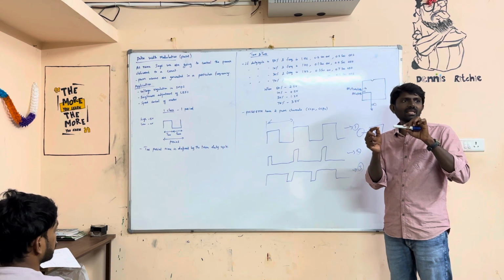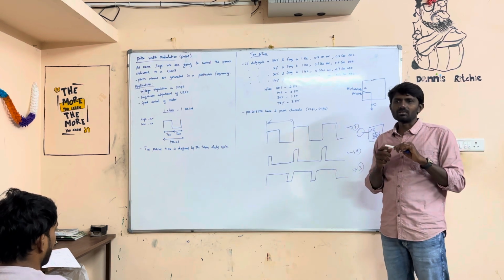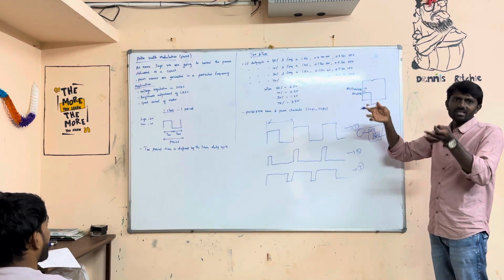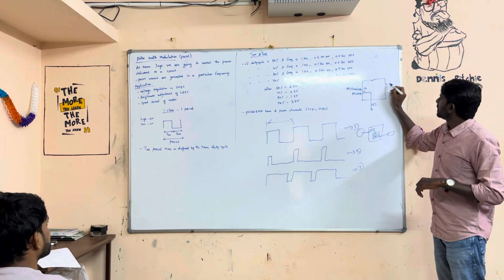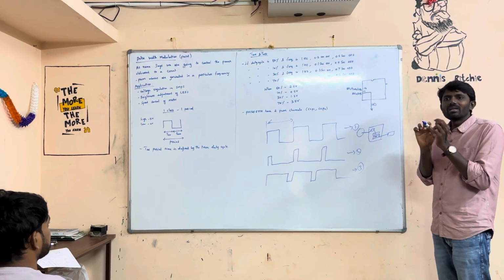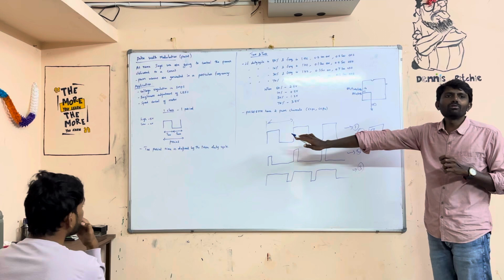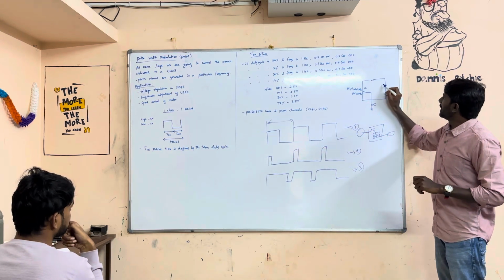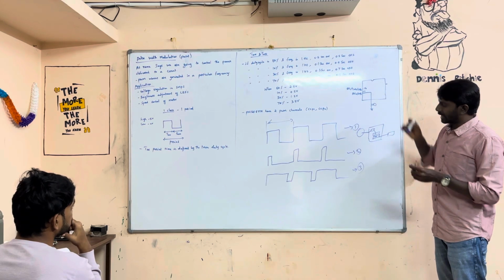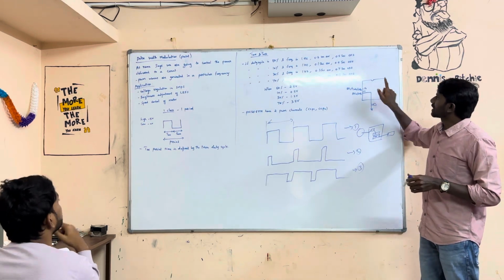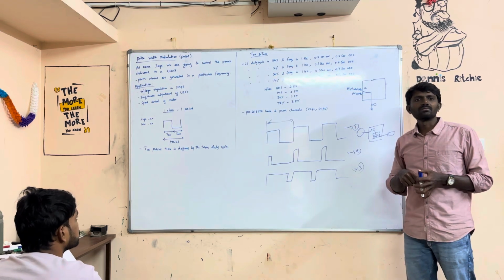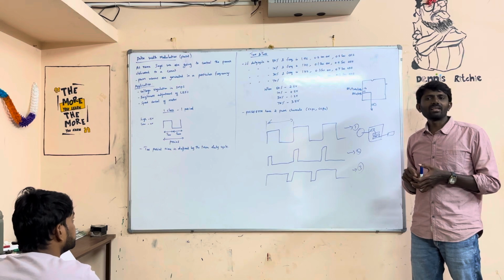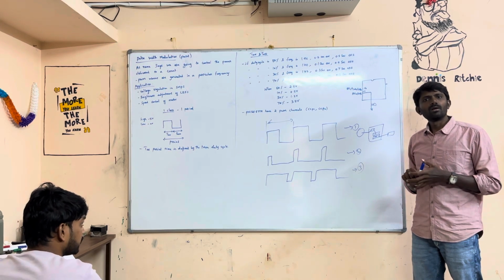Is everybody getting it? The same thing happens in this case also. There is one pin. Which pin, that will come later. In this pin, we are making the duty cycle 50%. Suppose your controller is working at 1 hertz speed. 1 hertz means how many clocks will it generate in 1 second? 1 clock, correct?